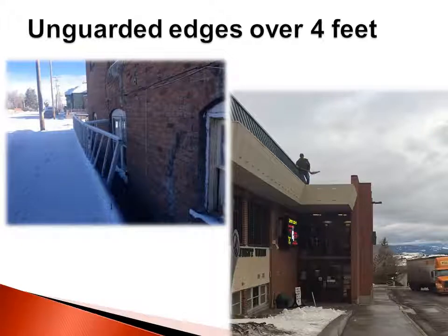And although it isn't his permanent place of employment, he's only up there temporarily, he could easily slip and fall off that edge. He could have put up some kind of barrier, maybe had some caution cones with some tape so he was able to visualize where that edge was, or had a spotter or a second person on site to communicate with him if he's getting too close to the edge.